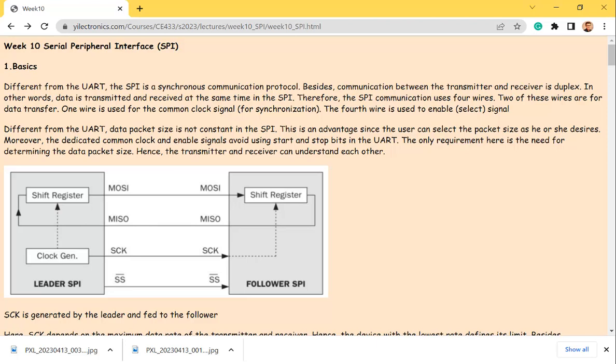So the SD card, most of the time the SD card modules have SPI ports. But sensors like the one-wire temperature sensor are very similar to I2C, but it's not I2C, just one wire. It's a totally different protocol developed by Dallas Semiconductor. And the accelerometer is totally just I2C. And the OLED display module is also I2C.